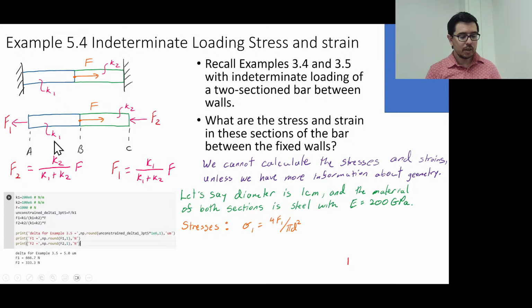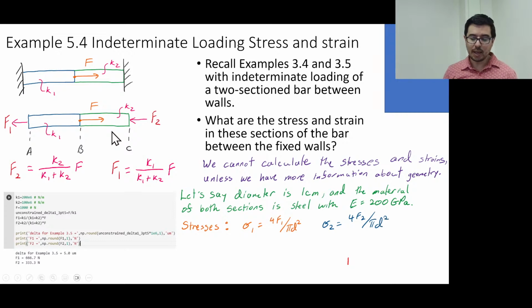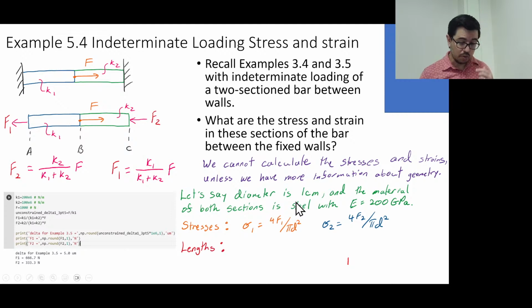In this region, they're going to be tensile. Okay, tensile meaning it's going to be pulling it apart, right? So that's because it's pulling it this way. Remember, this force is going to be pushing it in, so it's going to be negative. All right, so it'll be a negative stress. Okay. So sigma 2 should be negative. I was waiting. Oh, there it is. It finally appeared. Okay, that was weird. It took a while, but it's negative.